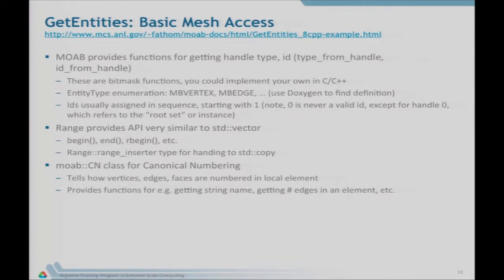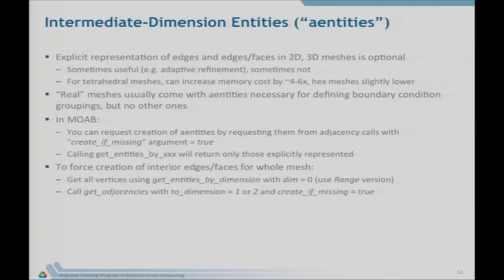What usually happens is somebody implements a triangle because they need a triangle, and a tetrahedron because they need a tetrahedron. And somebody 3 years later asks them, well, I want to do a quadrilateral. Can you do that? And oh no, I forgot to implement the quadrilateral in my numbering, and everything has to go back. So using a system like this gives you all that numbering from the start and a way to query it.